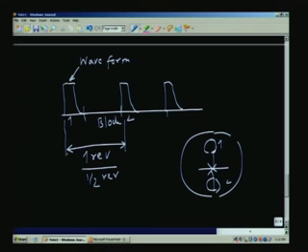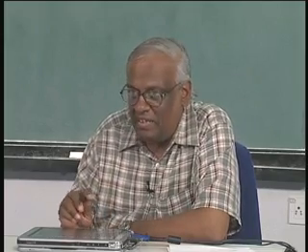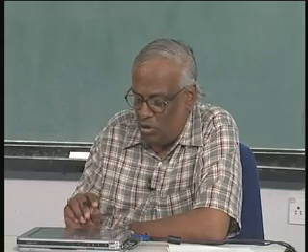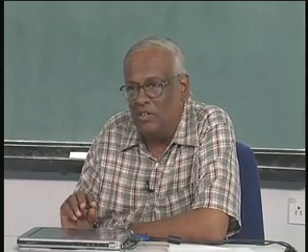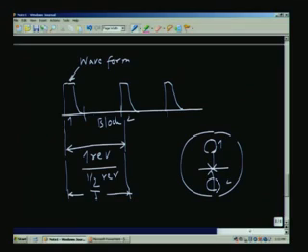So, if you measure the time taken from here to here, we will call it t, then this t will be either equal to 1 revolution, the time taken for 1 revolution, or it could be half a revolution, or if I have 4 of them, you can see that you can now get a signal. Every time a hole comes in front of it, you are going to get a small blip or an output, and the rest of the time it is going to be 0, and therefore, it is actually the number of times the hole is coming in between the light emitting diode and the photodetector. So, the time here can be related to 1 revolution or half revolution or a quarter revolution and so on. Therefore, we can see that t is related to per revolution.